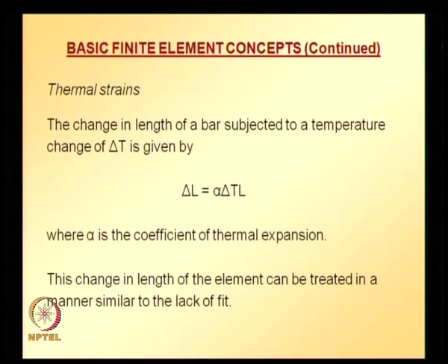And this change in length of element can be treated in a similar manner as that of lack of fit, because now because of temperature change there will be change in the length of the member which exerts some kind of force on a given structure. So, analysis proceeds in a similar manner as that of lack of fit. So, now let us take a problem to understand the various steps involved.